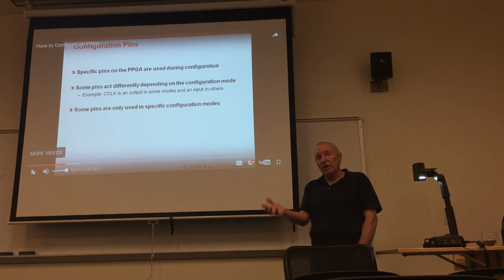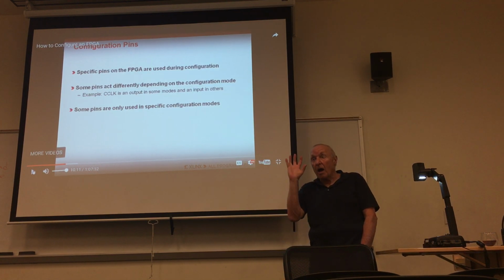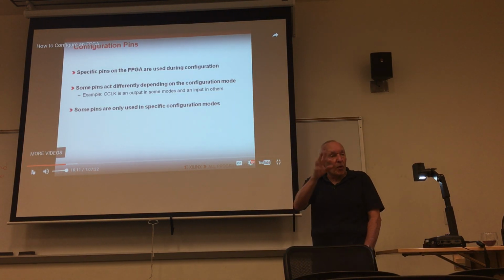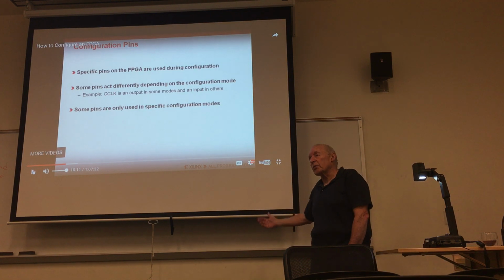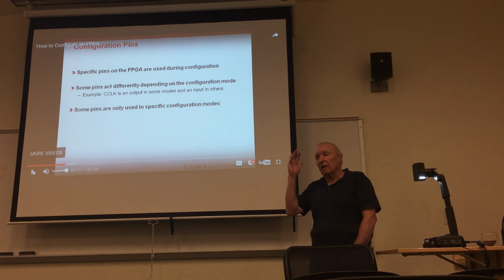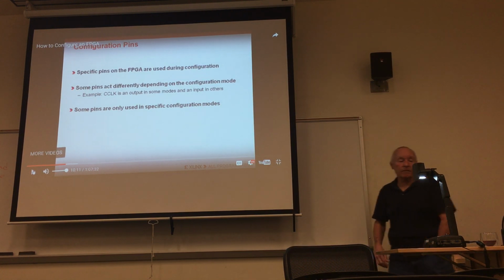So when the FPGA is first powered up, it goes and looks at those 3 pins and says, I'm going to get my configuration information from X. And you'll have one pattern you put on if you're going to do it through serial flash memory, another one if you're going to use the JTAG interface or a microprocessor or what have you. So it's through those 3 mode pins that the FPGA will find out where it is supposed to go to get its configuration information.